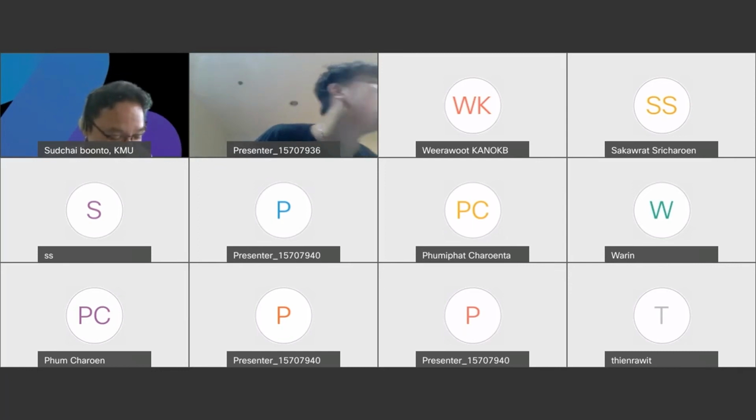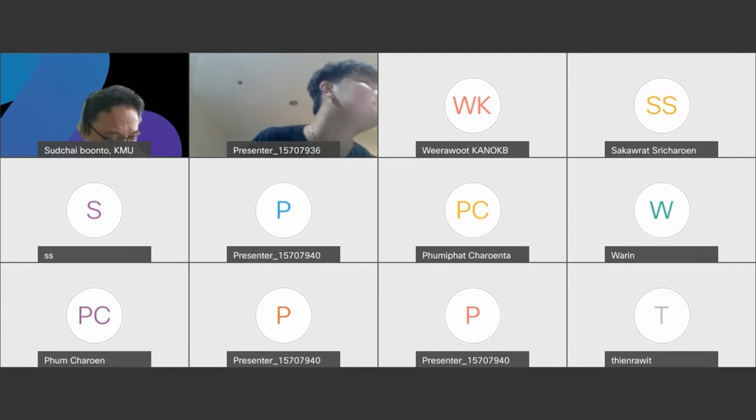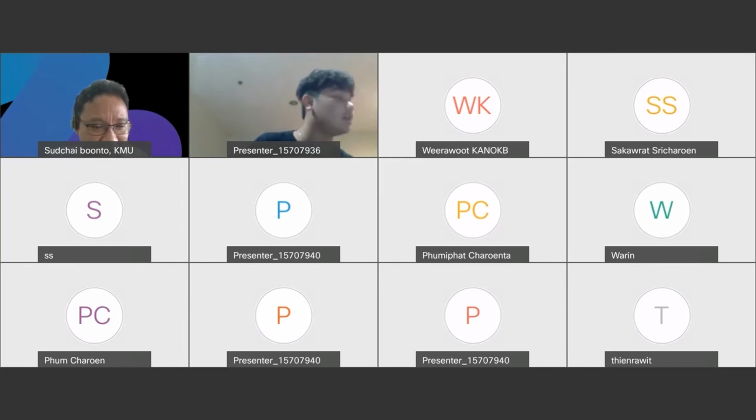I have one more question about your bandpass filter and notch filter. You said in the presentation that you used a bandwidth for the bandpass filter between 20 Hz and 500 Hz, right? However, the notch filter is at 50 Hz, which is in between the bandpass frequencies. Why did you do that?